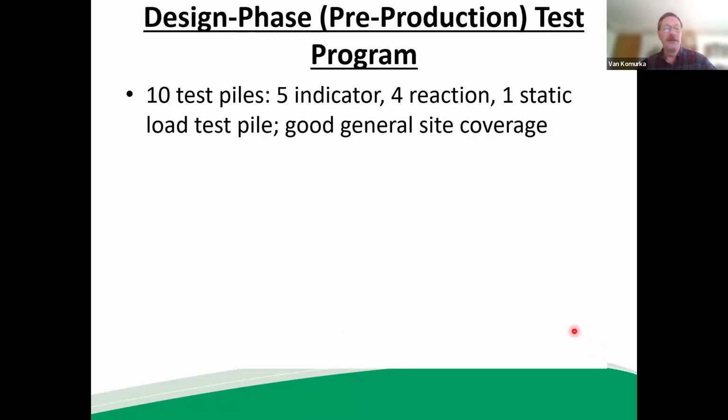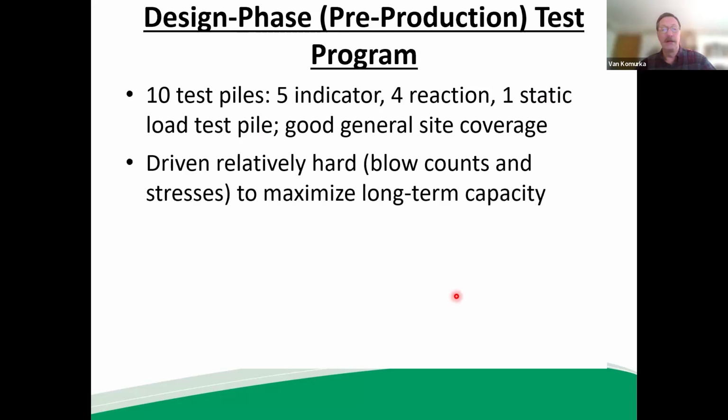Test program consisted of 10 test piles, 5 indicator for reaction, 1 static load test pile with strain gauges, and it provided a good general site coverage. We drove the piles hard, both high blow counts and near their driving stress limits. And by the way, that's the most economical installation.